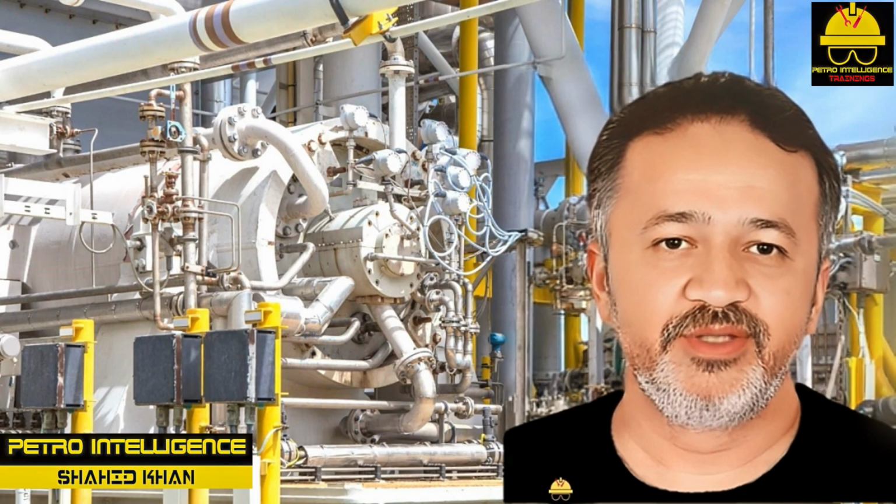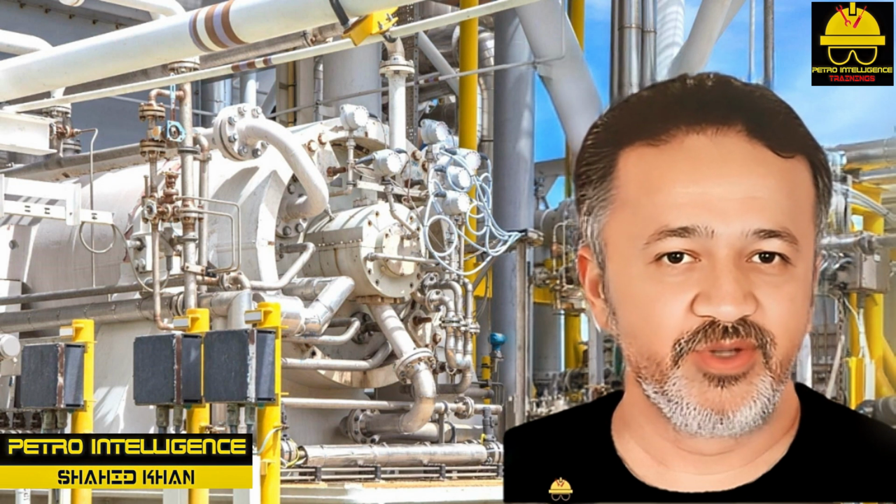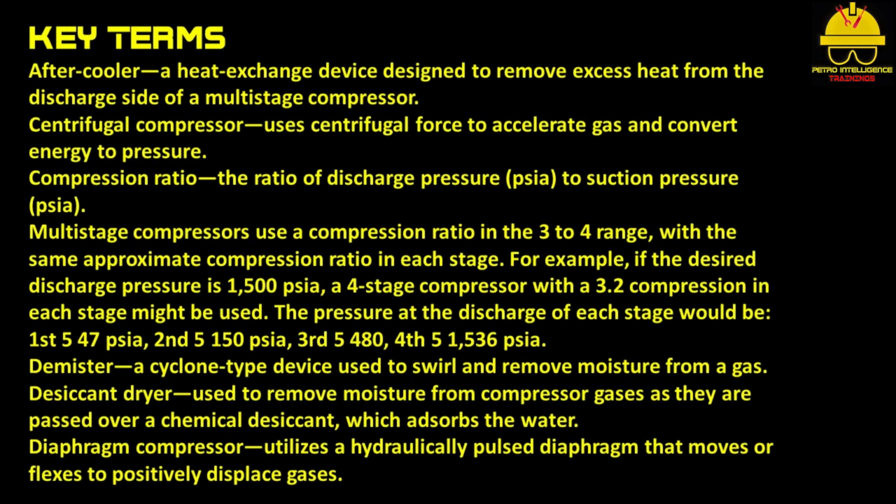Before starting the course, let's have a look at key terms of compressors. Aftercooler is a heat exchange device designed to remove excess heat from the discharge side of a multi-stage compressor. Centrifugal compressor uses centrifugal force to accelerate gas and convert energy to pressure. Compression ratio is the ratio of discharge pressure, PSIA, to suction pressure, PSIA.